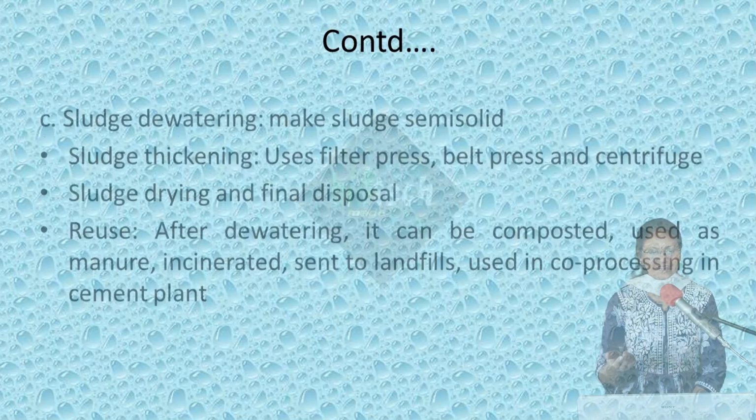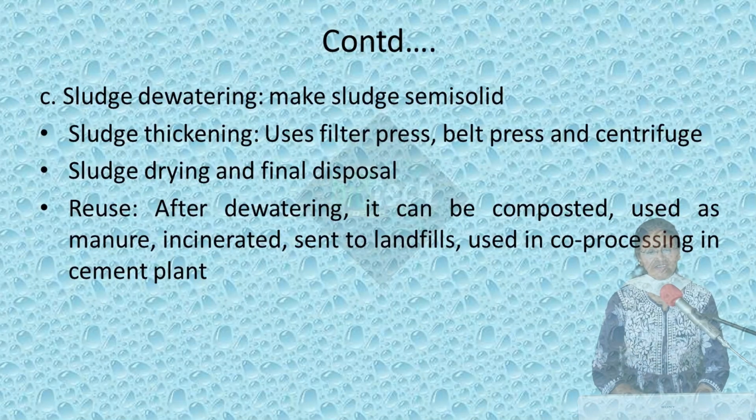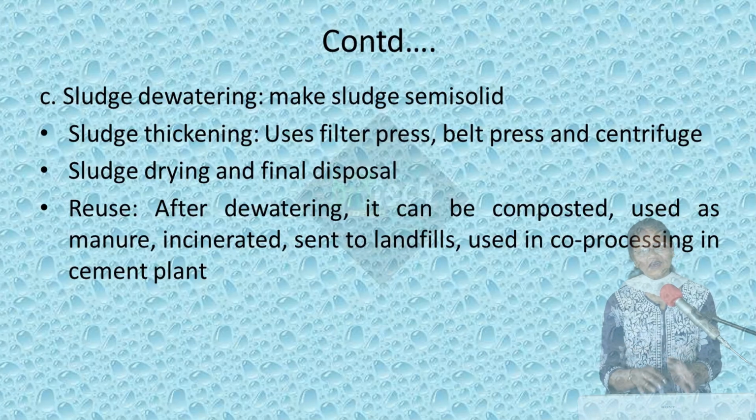Then next is sludge dewatering. So it makes the sludge semi-solid, because here almost all the water is removed, and this is done using a filter press, belt press, centrifuges, etc. Then you do the drying, and then after the drying the final disposal is done.